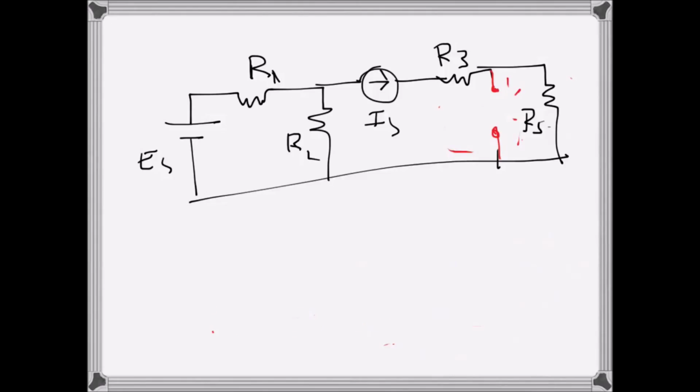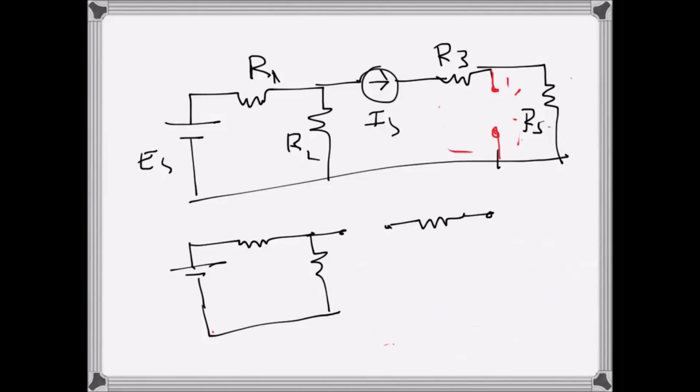First, if we consider the voltage source, it becomes like that, and when we consider the voltage source, the current source has to be inactive, so it's again an open circuit, and then we will see the open circuit voltage across terminal AB.